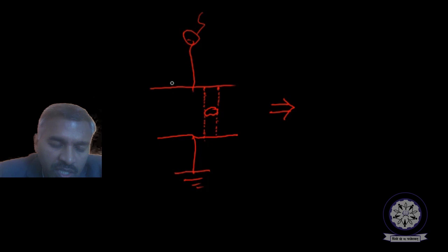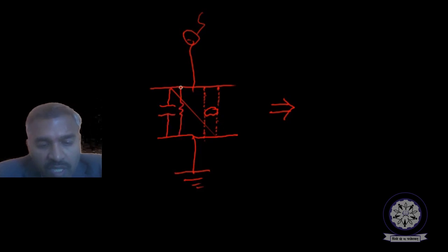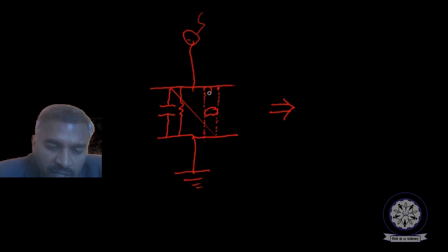The rest of the dielectric, except for the void, is represented by a capacitor in parallel with a resistor. The upper portion is again the same representation, a parallel combination, and the bottom also in the same way, one capacitor and one resistor in parallel.